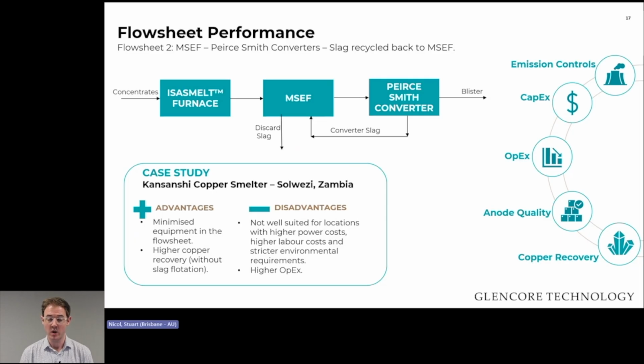Higher labour costs as well. The MSEF generally uses a lot more operators on the tapping floor to open and close the tap holes for the slag and the matte there. And it can also have a higher OPEX depending on the configuration, the location and what goes on.